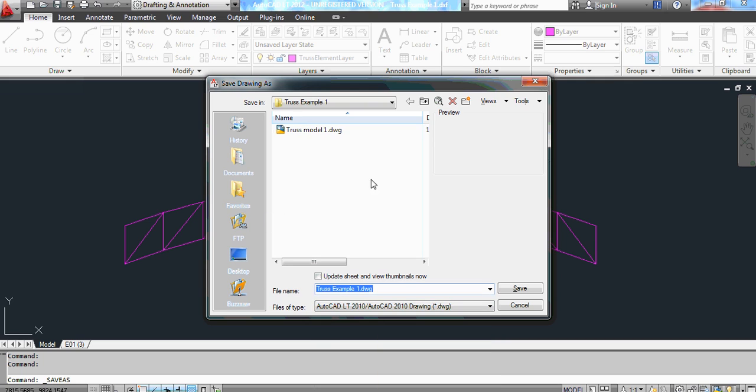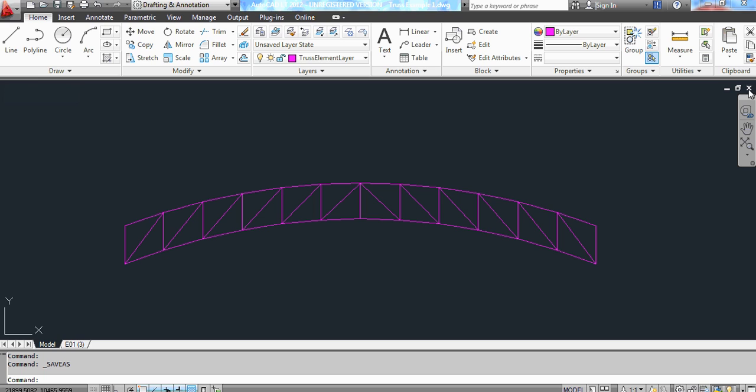So that means that we have two copies. You have a DWG copy which you can always open, because sometimes the DXF might not open, and then you also have the DXF. DXF is just for you to be able to read it in Quick Structure 7. But before you ever read in Quick Structure 7, you must close the DXF, or else it will not read. So let's go over and read it in Quick Structure 7.